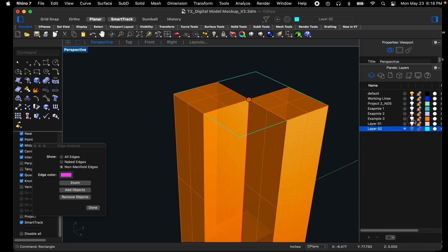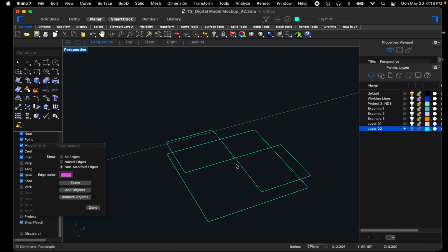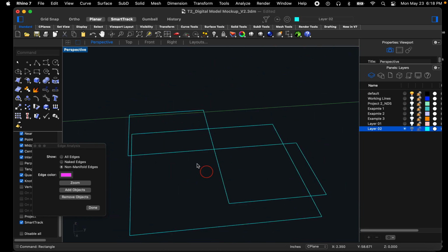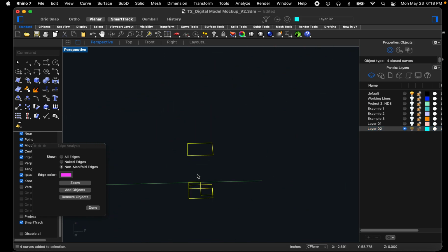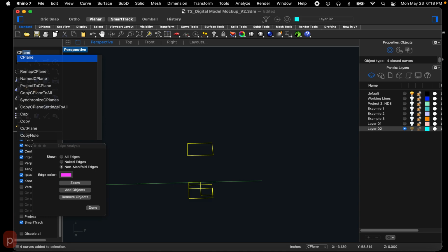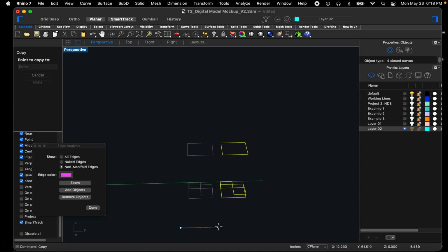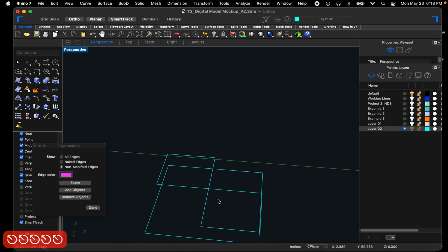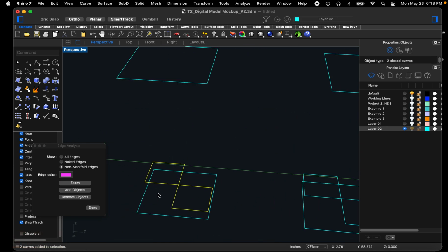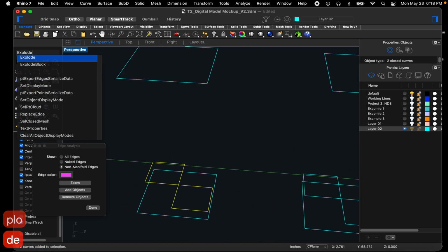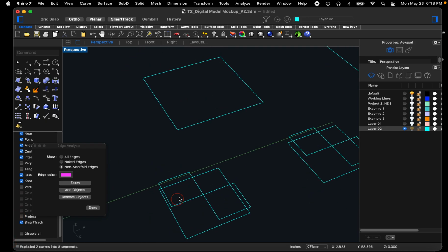Okay, I'm going to turn this off. Now I'll take this, and I'm actually going to make a copy, and I'm going to turn ortho back on. Now I'm going to take this and I'm going to explode it.